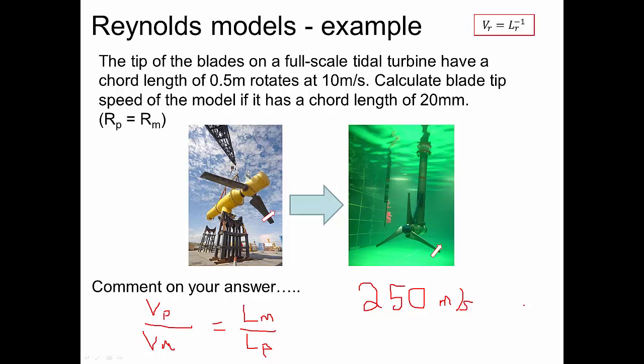So what we have to do is basically scale the Froude number, so keep parity of that, and take a hit on the Reynolds number. So the Reynolds number across the blades is what it is. We can try and make the rotor spin a bit quicker, and we can obviously make the blades a bit thicker, or a bit wider, sorry, to try and increase that Reynolds number. So when we do our tests, our Reynolds numbers are about 1 × 10⁵. So it's an order of magnitude lower